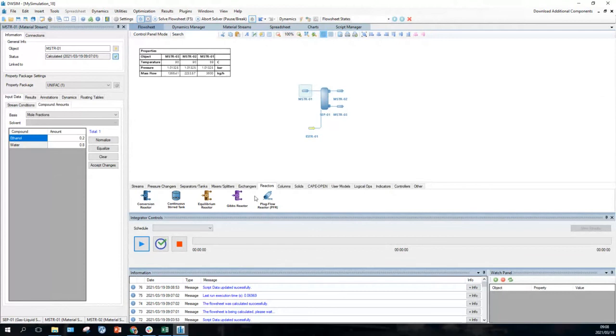Okay, reactors. Now, in design project, you are almost certainly just going to use conversion reactors, because when you do your literature review about this process that you're designing in your design project in CPJ, you're going to learn that it is difficult to get anything more than, say, 70% conversion.